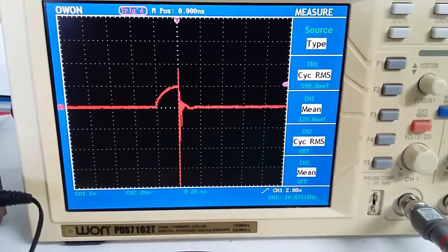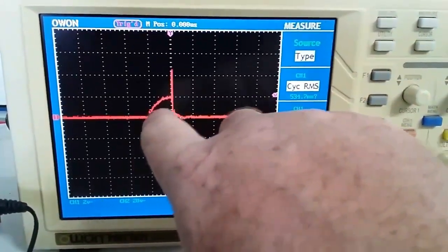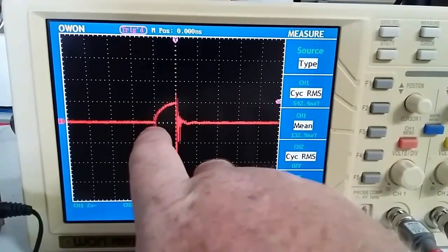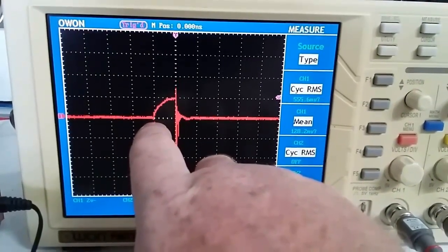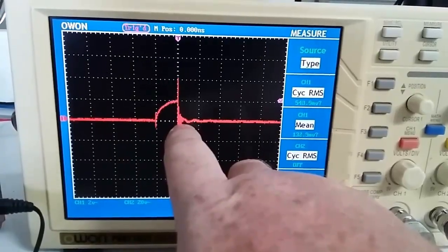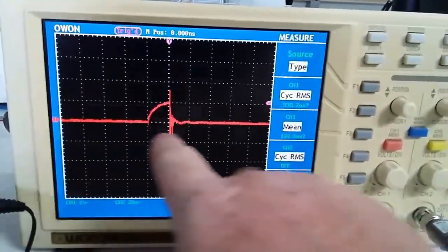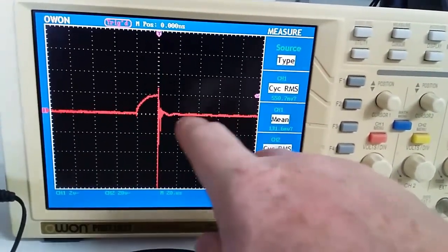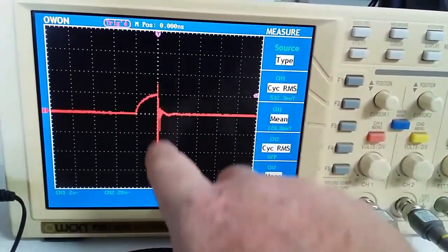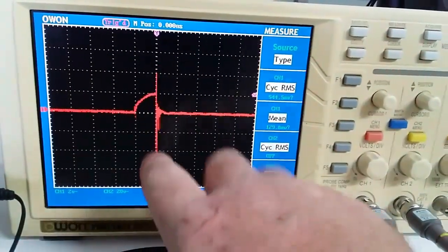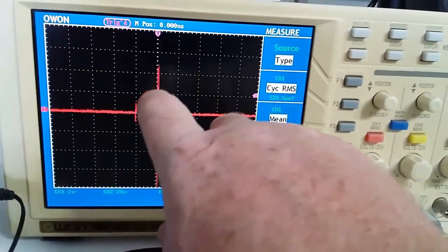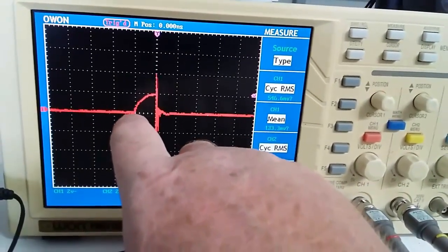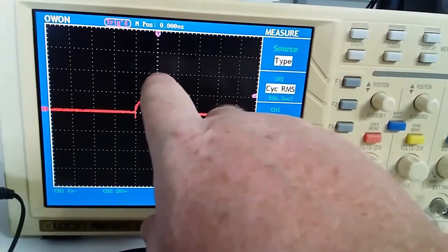Now what we're seeing there is the ramp up of current. Okay, so this is the change in current. Now I just want to explain, because we talked about rise over run. Okay, the run is the time, which is the x-axis. So if you look, the x-axis runs across this way. Okay, the rise is the y-axis. The y-axis runs up that way. Okay, so rise, which is that, over the run. Or if you want to explain that even better, the rise over the run.